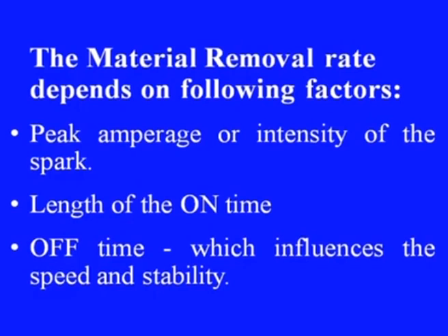The material removal rate depends on the following factors. Number 1, peak amperage or intensity of the spark, the length of the on time, and the length of the off time, as I have already indicated, which influence the speed and stability of the sparking.